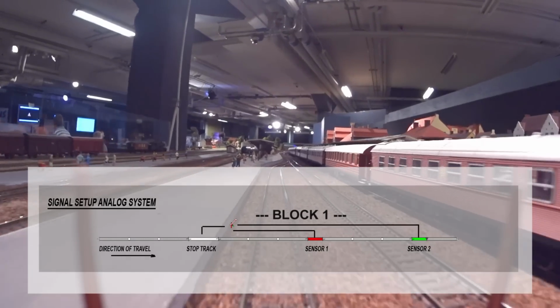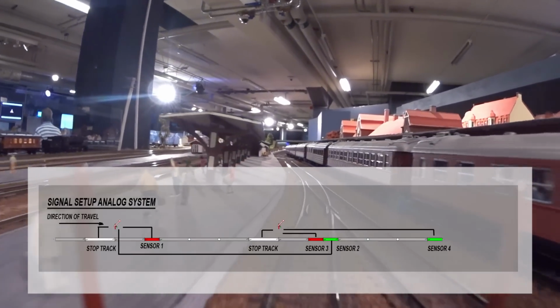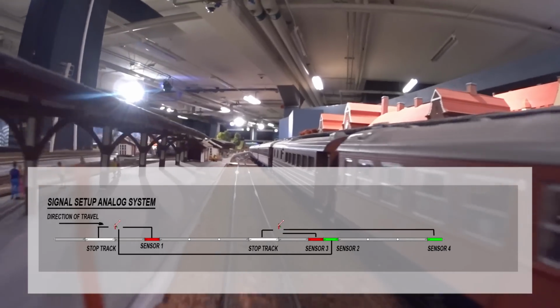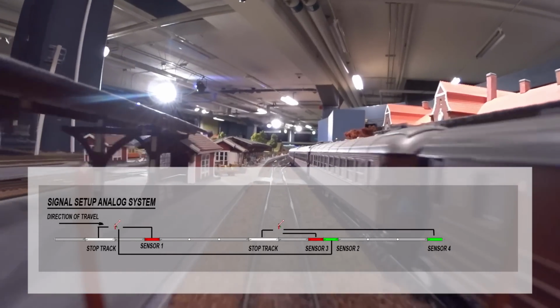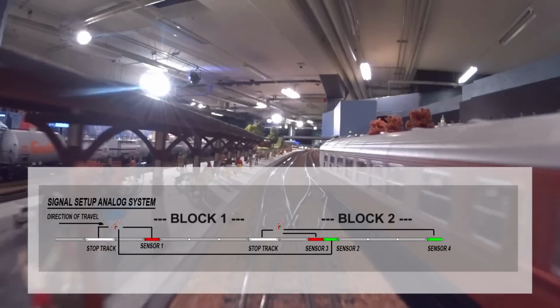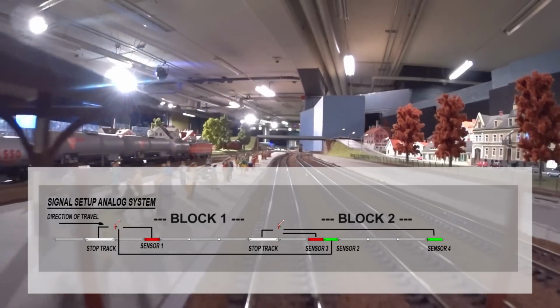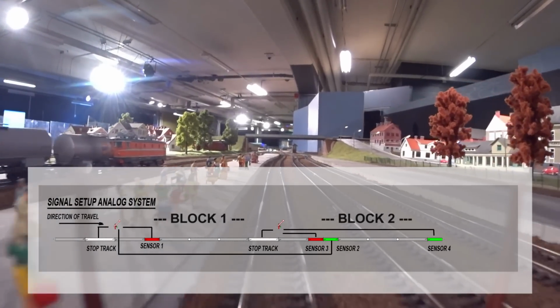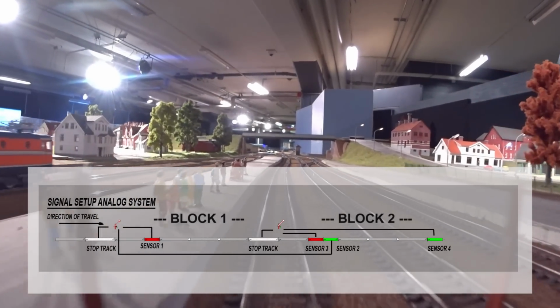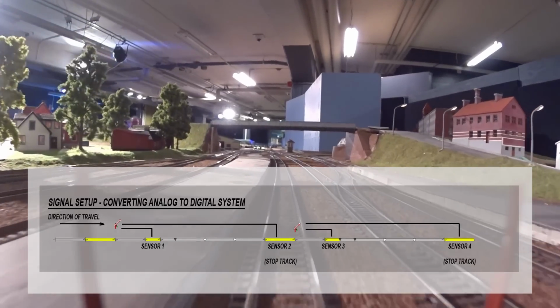Now, when two blocks follow after each other, which they typically do on the layout, the only difference is that you move sensor 2 from the first signal to behind the first sensor for the second signal. This will assure that the first block is not ready for new trains until the first train is fully into block 2. Otherwise, everything's the same.